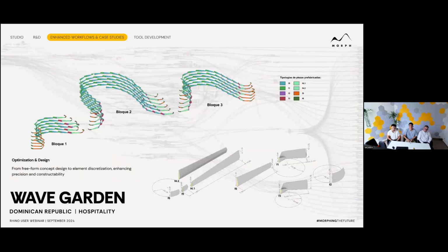These intertwined parapets that you can see over there are executed in glass fiber reinforced concrete. As you probably know, these parapets are created with molds, and each different kind of mold impacts directly on the budget. So rationalizing them was key to make all these free-form designs constructible, maintaining cost efficiency.